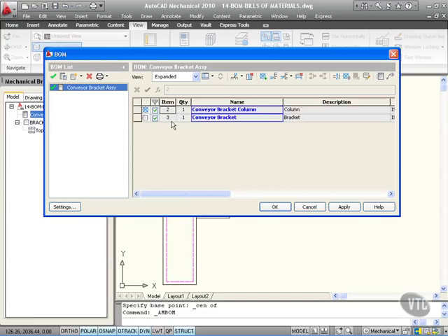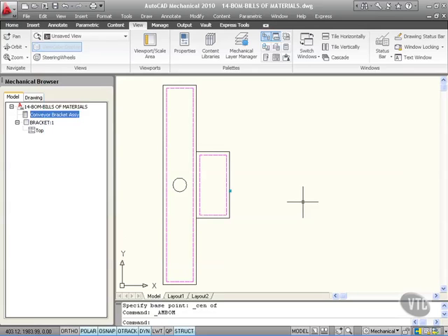So it's listed them and numbered them and given them a quantity. So this will start to build up. Now I've got a very basic one here, but if you've got a very complicated mechanical drawing, this is where you can start actually basically iterating every single part of your assembly or your design. So I'll just cancel that for now. So you can see there how your BOM, B-O-M, or bill of materials can be built up utilizing your part references in your drawing.